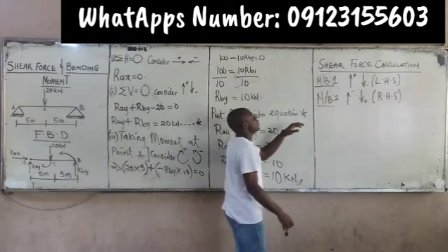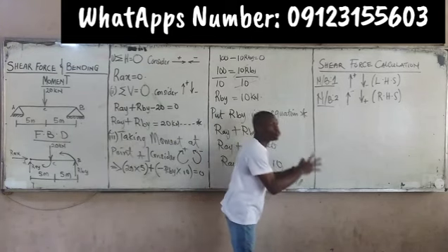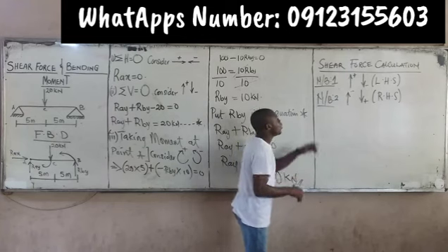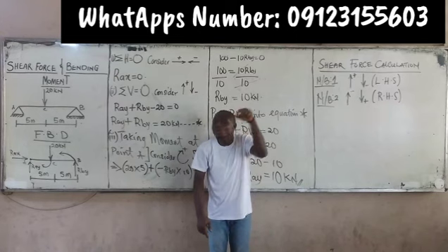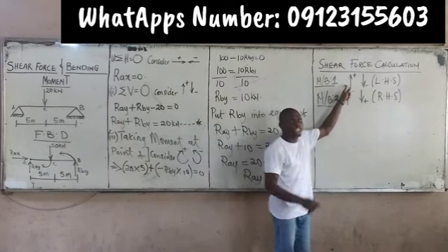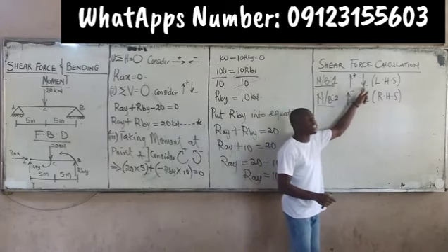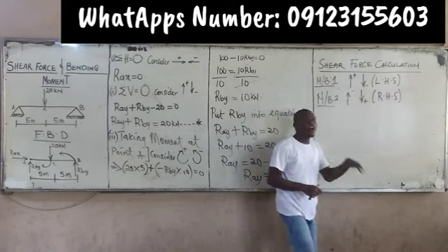Alright, we said for shear force, note two things. Number one, whenever you're taking readings from left hand side, ensure that upward force is positive, downward force is negative.